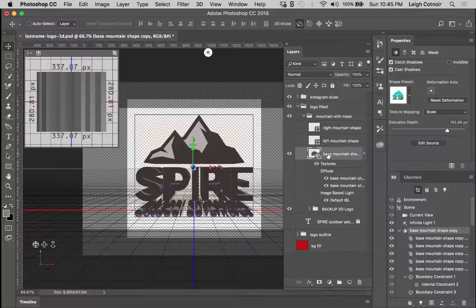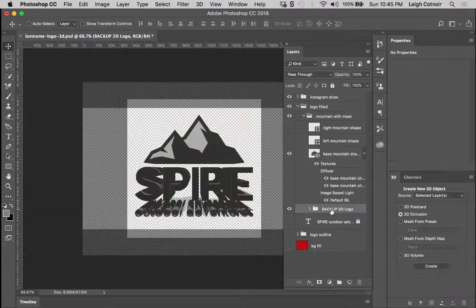that you're adjusting something in the 3D layer, you've got to make sure that the layer is actually selected in the layers panel. And you'll notice right here where I'm circling my cursor, there's a little cube that gets placed on top of the thumbnail in the layers panel for that layer. That means that it's become a 3D object. All right, and so that way you'll know that that is a 3D object. You'll notice whenever I go and select some other layer, let's just select this, all of the 3D stuff goes away so that I can't accidentally move something according to the other layer.